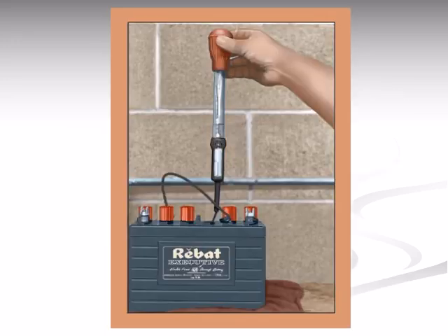In this image, we see a technician using a hydrometer to check the specific gravity of the electrolyte in a lead-acid battery. This test is an important part of battery maintenance. By drawing a sample of the electrolyte into the hydrometer, the technician can measure its density compared to water. The specific gravity provides a direct indication of the battery's state of charge. A fully charged battery typically reads around 1.265, while a discharged battery may fall to around 1.120 or lower.